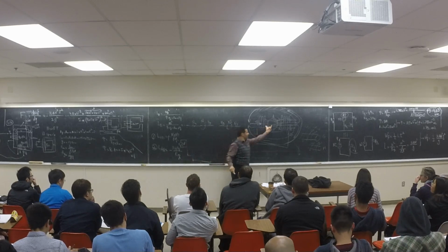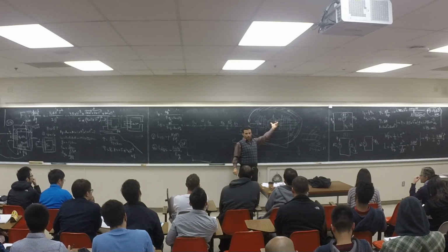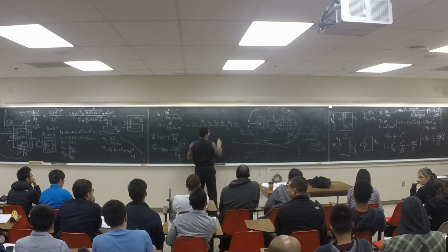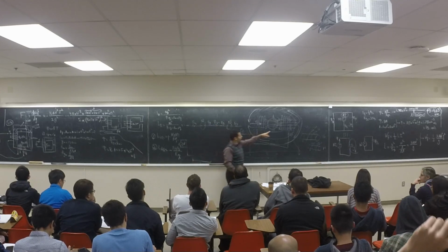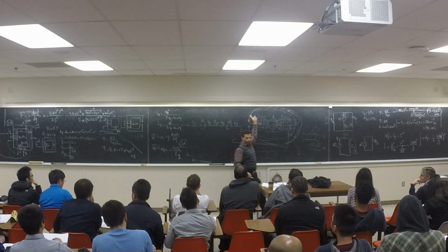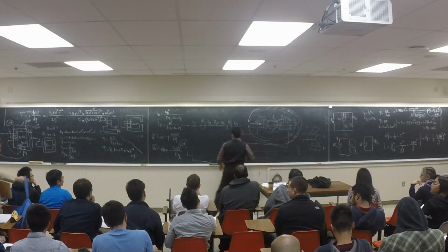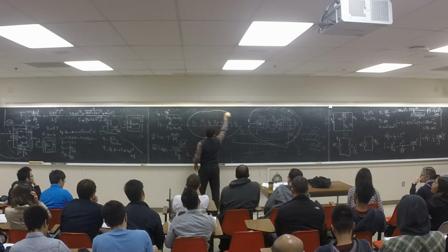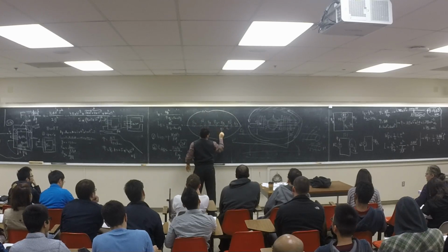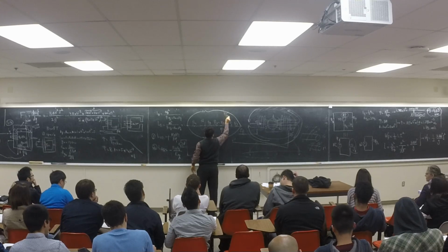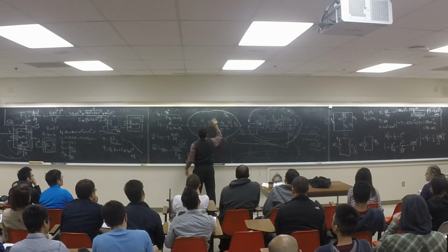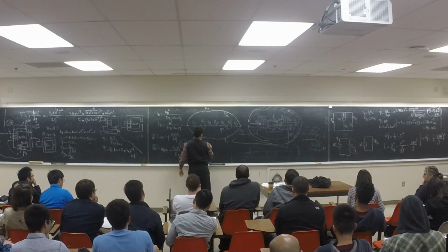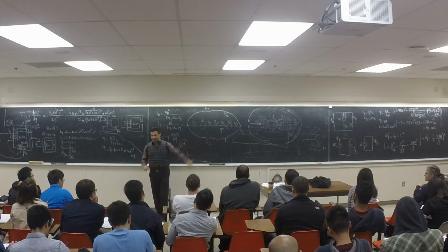I'm going to have one in the middle because of the iron of the rotor, so it's going to be RR. And one here and one there. Flux is going like this. Half of P is coming this way, half of P is coming this way, and this is, for example, R2, R3. So that's the circuit for that excitation.